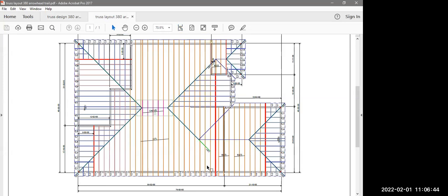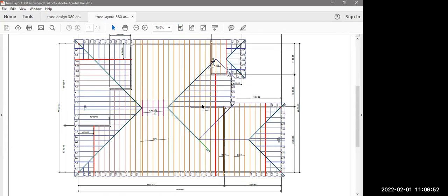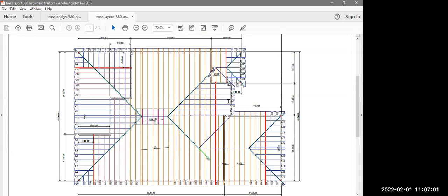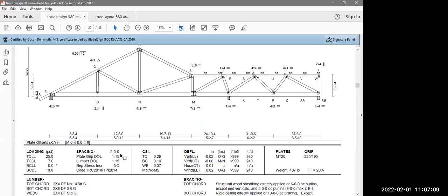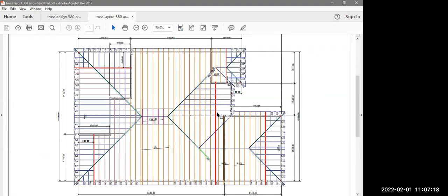So what I've got to do then is figure out where this truss is. Let's see, do I have any dimensions to it? Doesn't look like you give me any great dimensions. I think it's 6 feet from this front wall right here, but basically I've got to decide where that is. You may remember that the 2,700 pound weight was at L in the middle here, the big one, the 2,745 weight. So I've got to go to this location inside the house and put a larger concrete footing there to support that, because the gist of it is that's more than 1,500. I need a 2 square foot footing right there, because I'm just sitting this house on the dirt, and dirt can't push back more than 1,500 pounds a square foot. So if I only have a small foundation underneath this, that's not going to work.